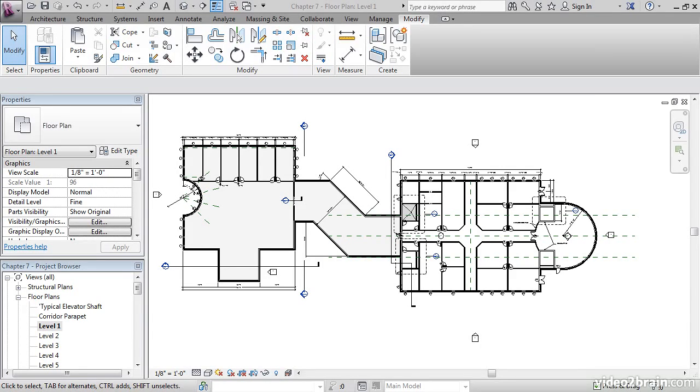In this lesson, we're going to be creating a shaft opening for our future elevators. Another problem with just adding one big floor, then copying it up 4 levels is, there's no way to get an elevator up through there. We don't have to worry about that. We can add what is called a shaft opening. It's pretty easy and it works pretty awesome.